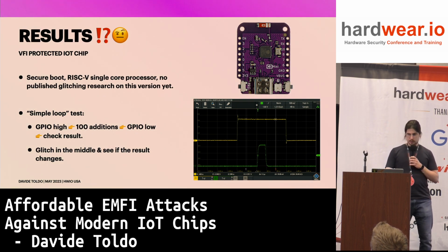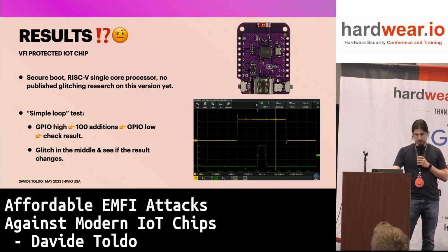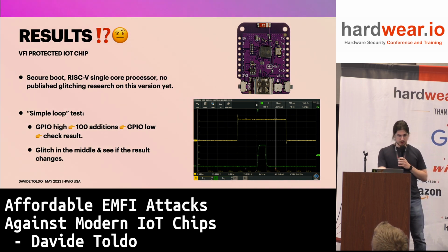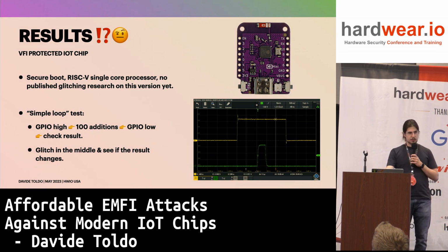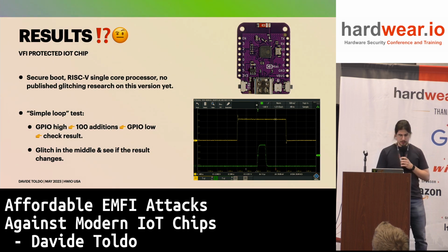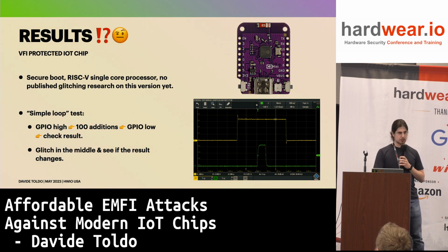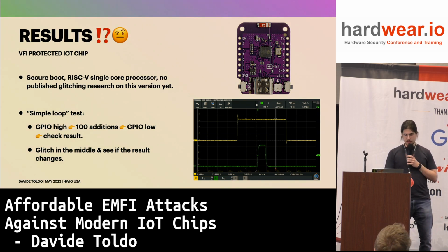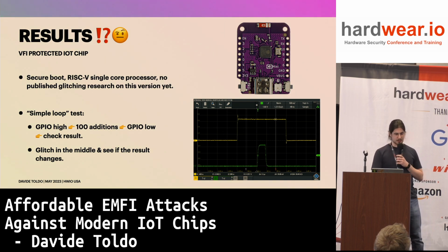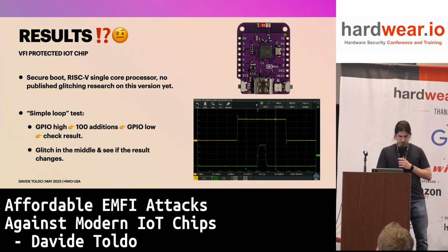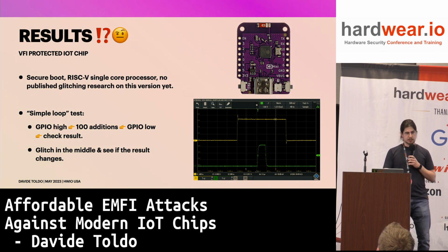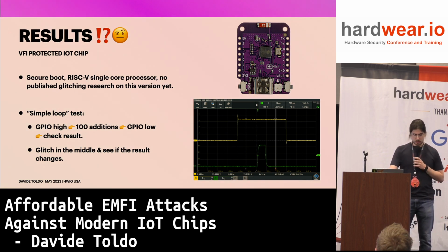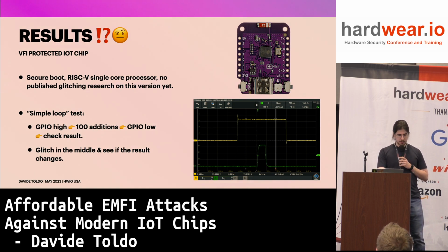I tested the setup on a quite modern chip, which you might all know. It's supposed to be protected against voltage fault injection, and there were many results on predecessors of this chip. They wanted to fix voltage fault injection, they wanted to fix side channels, but apparently EMFI still works. It also has secure boot and different other features that should all be attackable through the same method.